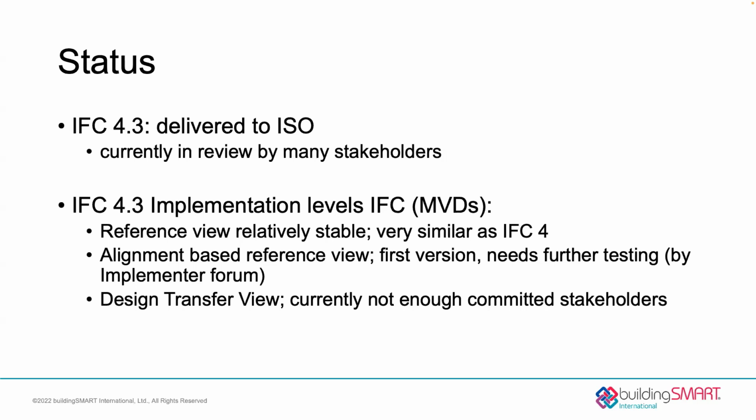Sorry, John was first. Yeah, well, this starts to dive deeper down the rabbit burrow, but coordination view: when you research why IFC2X3 persists, for me one of the reasons we still recommend it is for material layers and other attributes that aren't in reference view. But coordination view is extinct? No. I'm not one of those persons that says 2x3 is so old we shouldn't use it anymore. It works perfectly for certain use cases.